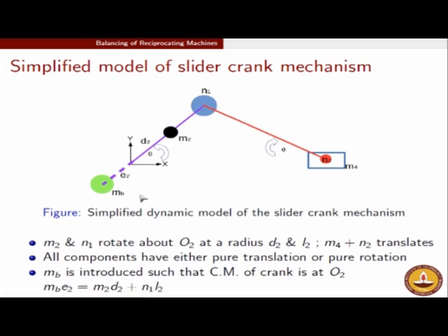balance this system. So that is exactly why you will see that in the crankshaft construction you will have webs in one direction. These webs are supposed to be the counterbalances which balance the crank mass together with the apportioned mass of the connecting rod which is sitting on the crank pin. So at this stage with this counter mass, what have we achieved? We have achieved our objective that there are no rotary unbalances left in the problem.